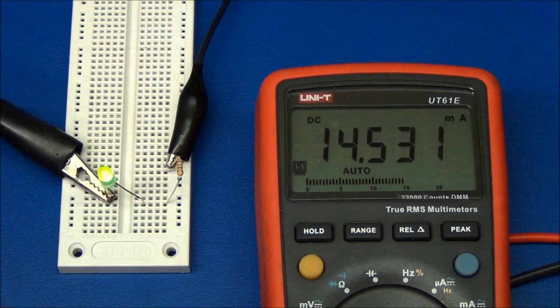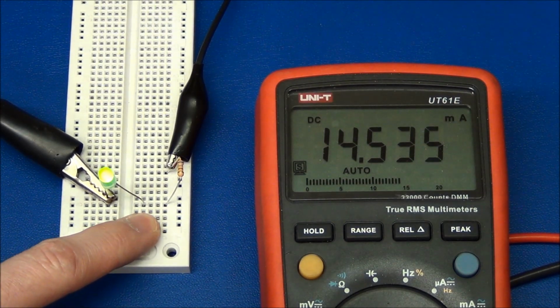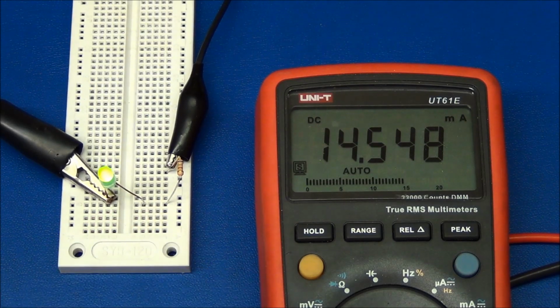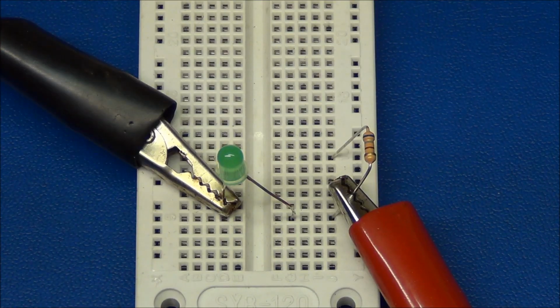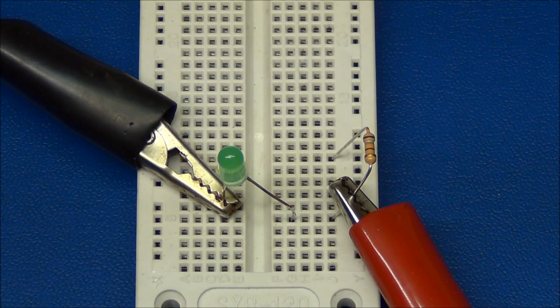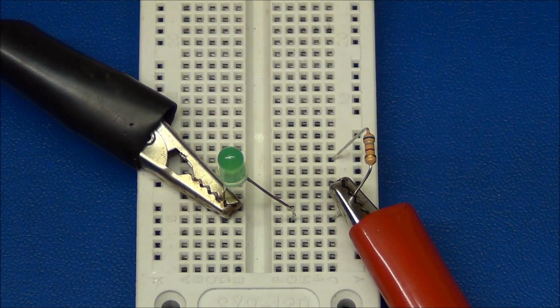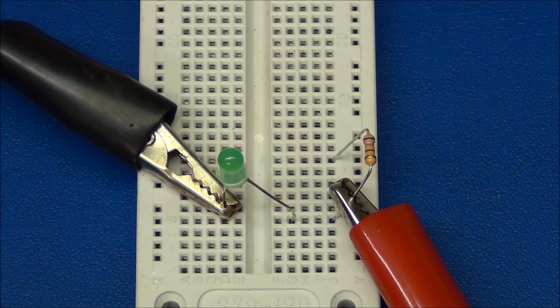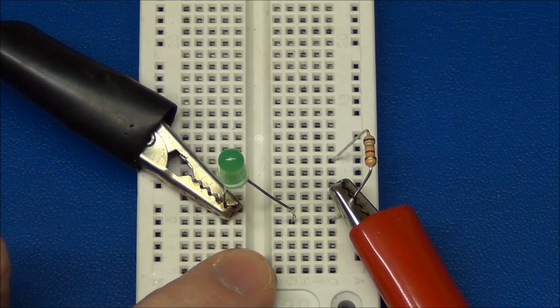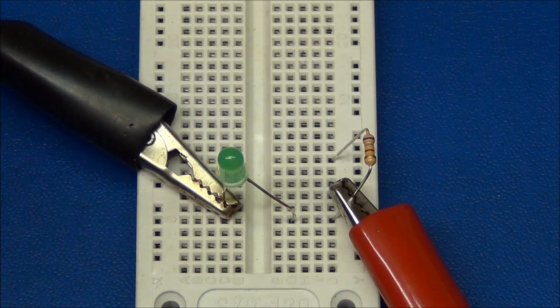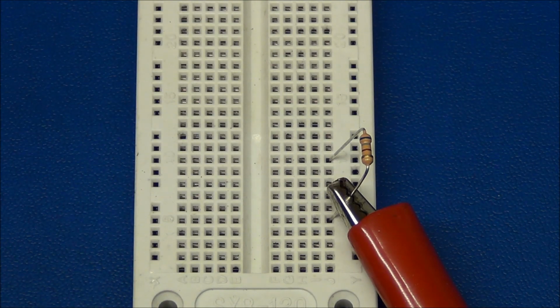So now you might wonder what would happen if this resistor was not in place, and we have connected the 12 volts directly across the LED. So why not try that? And before doing this, I removed the ammeter from the circuit. Now let's see what will happen. And as you saw, that just died very fast. But it actually can be much worse than that, and I'll just put a clip in from a previous video I made.